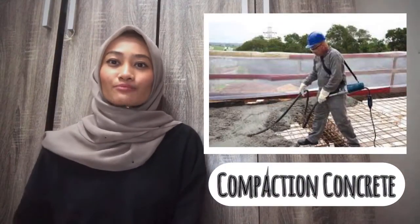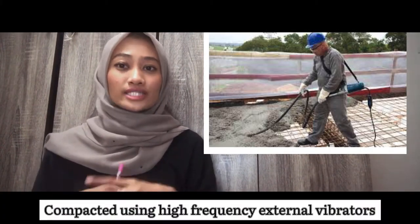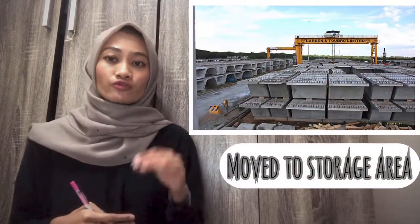Fourth is compaction of the concrete using a poker vibrator, to ensure that optimum density is obtained and that the specified strength is achieved. The concrete is placed and compacted using a high frequency external vibrator. Next, this figure shows the precast concrete being moved to the storage area.